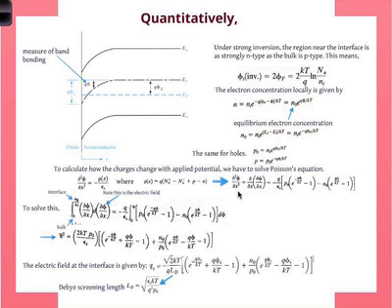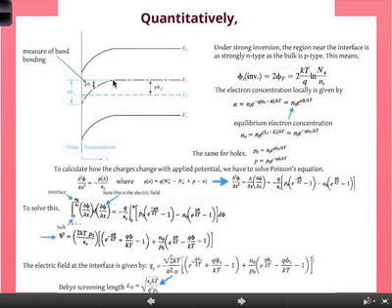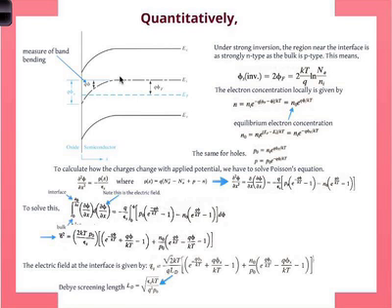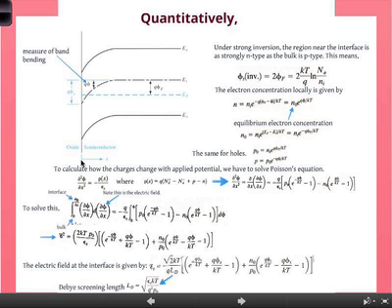Remember, what we have done now is we are trying to solve for the curvature of the band. How does this curve? Because if we know that, we know the relation to the voltage, because the band curvature is related to the voltage. So solving this is not that difficult. You can simplify the differential equation as shown here, and then do an integral from the bulk far away in x to the interface where you have some applied field.